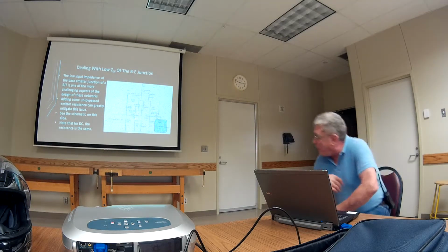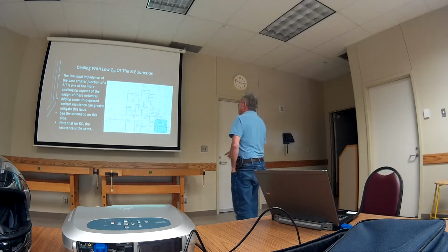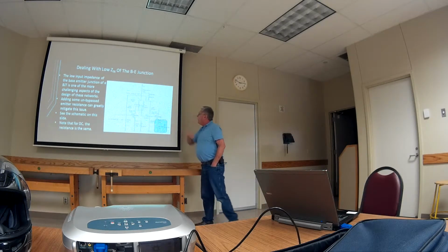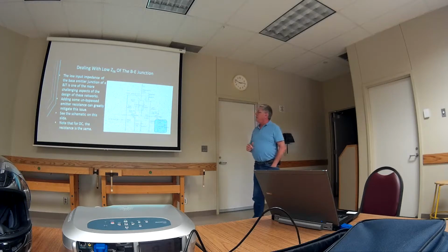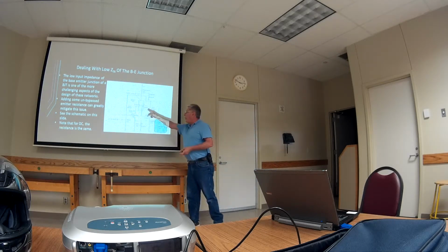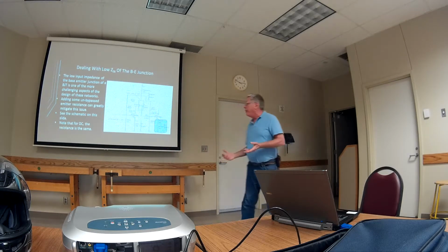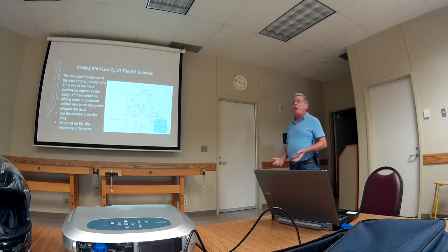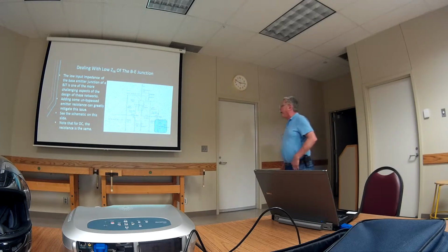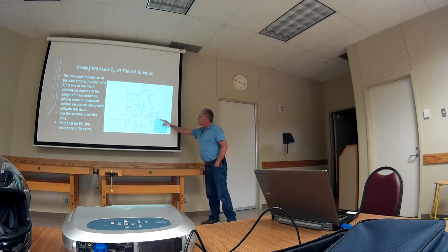Well, this guy, as I mentioned before, the input impedance of this guy, it really gets ugly sometimes. Like, I've had experiments where I'm chugging right along, everything's working good, and it turns out I need to tap my coil at like 1/10 of a turn because that impedance is so low. Well, you're not going to do that. Rather than go back and start redesigning everything, you can do something like this.